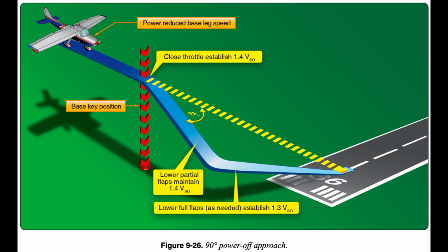At this position, the intended landing spot appears to be on a 45 degrees angle from the airplane's nose. The pilot can determine the strength and direction of the wind from the amount of crab necessary to hold the desired ground track on the base leg. This helps in planning the turn onto the final approach and provides some indication of when to lower the flaps.